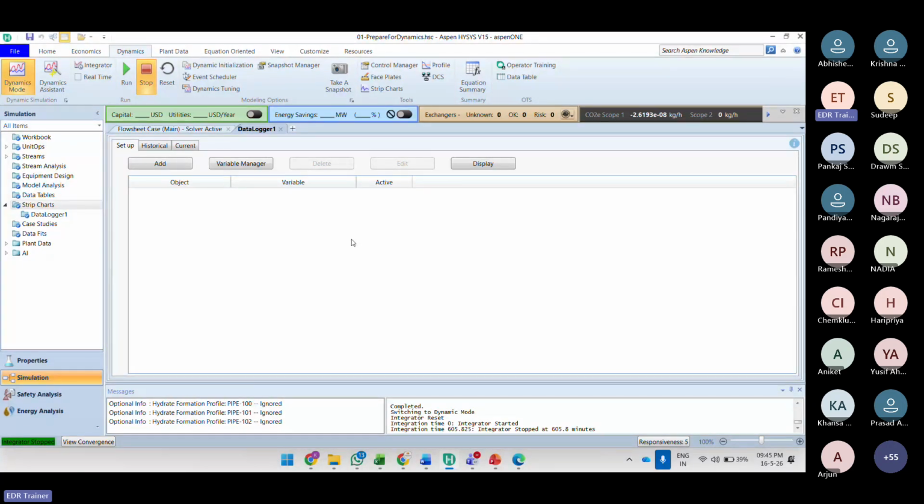A steady state simulation will not run if a basic principle is violated. But in dynamic simulation, normally, it will give you some results. Whether those results are meaningful or not, you have to make a judgment of your own, or you can go to an experienced person who can help you understand whether the actual system would also work in the same manner. That is a very important thing.